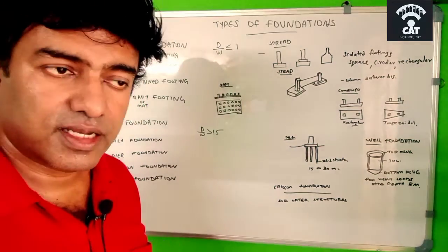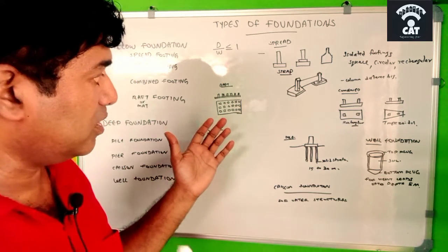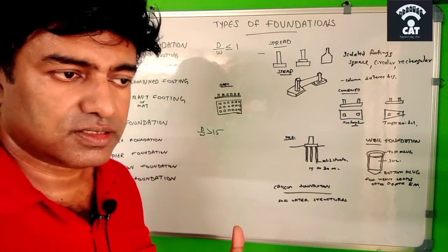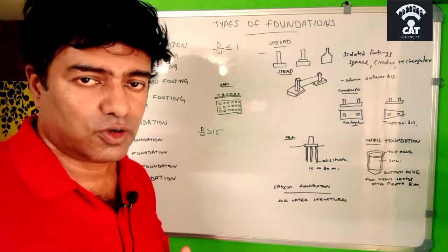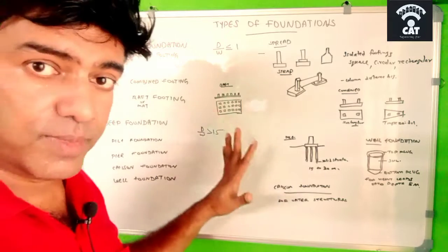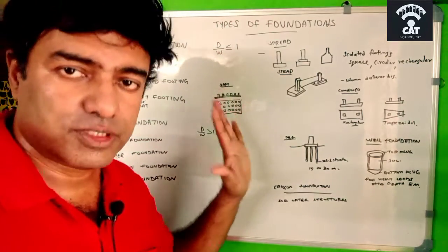And the second condition is that when the load per column is very less, then also it is not necessary to provide a single base to all the columns. Instead we can go for mat footing, but all this depends upon the bearing capacity of soil.